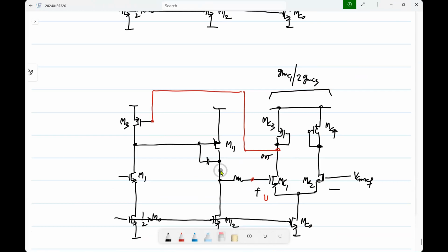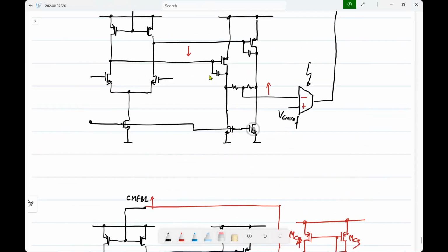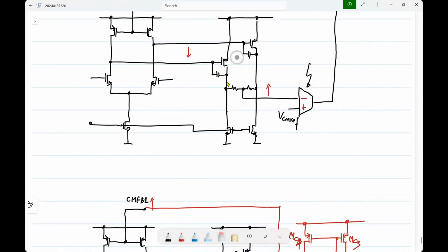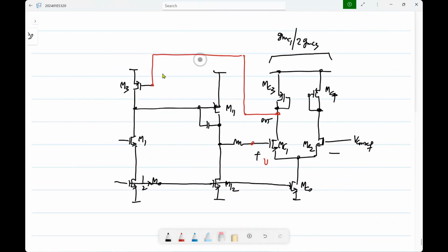Okay. So what will you need to stabilize such a thing? You have two stages. What is it that you need to stabilize? So this capacitor is there for the fully differential op amp, right? So we have these capacitors in the fully differential op amp, and that will appear in the common mode picture also. So that itself, now you can see it's like a two-stage Miller op amp. Okay, so this itself may be sufficient to stabilize it. So then you don't need to put anything extra other than, of course, this you may still have to do if the resistor is large.